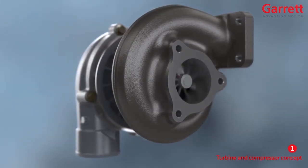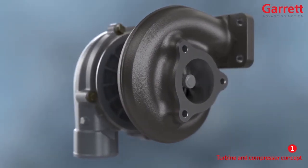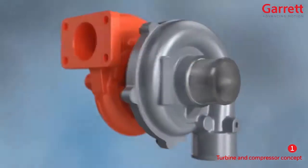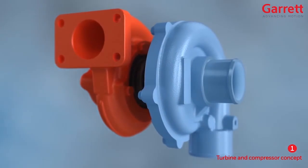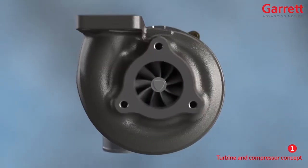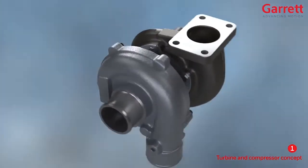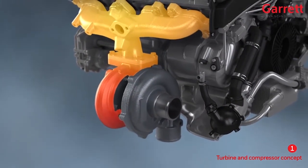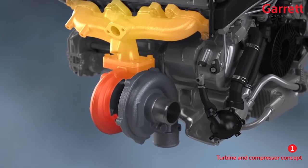The turbo can be separated into two distinct sections: the turbine stage, which is the hot end, and the compressor stage, which is the cold end. The turbine is driven by the waste exhaust gas from the engine, and that in turn drives the compressor, which draws in ambient air and compresses it.